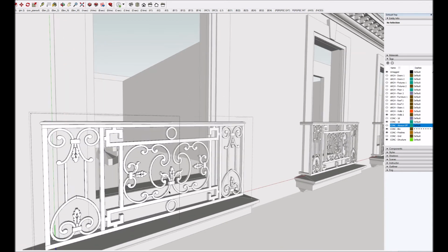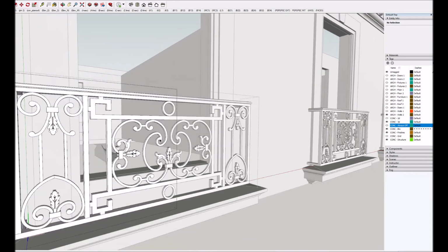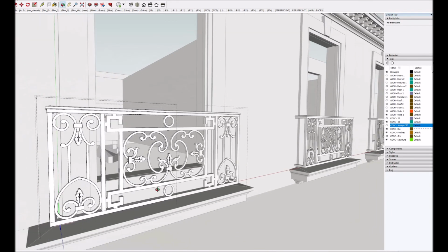I drew a rectangle and grouped it so that it was easy to edit without messing other things up. And then within that rectangle, I would draw a single curve. And then I would use the offset tool to offset a parallel curve. Close the ends so that it creates a complete solid surface. Erase the bits of the rectangle that I didn't need, and then extrude what was left. So that was the process I used for building up all those shapes.